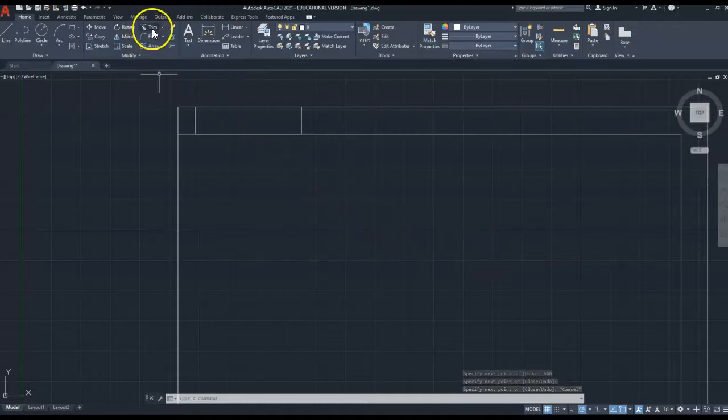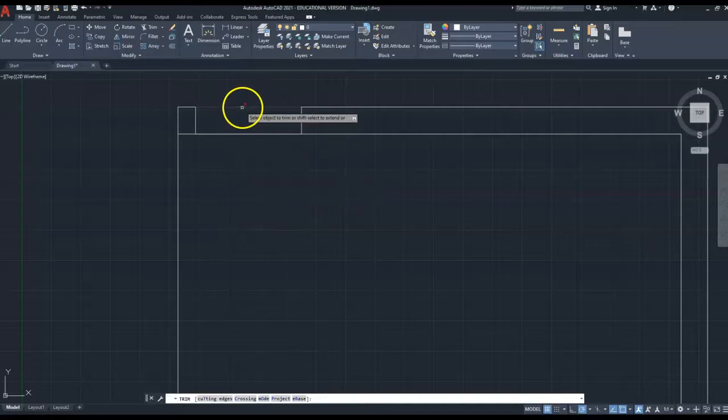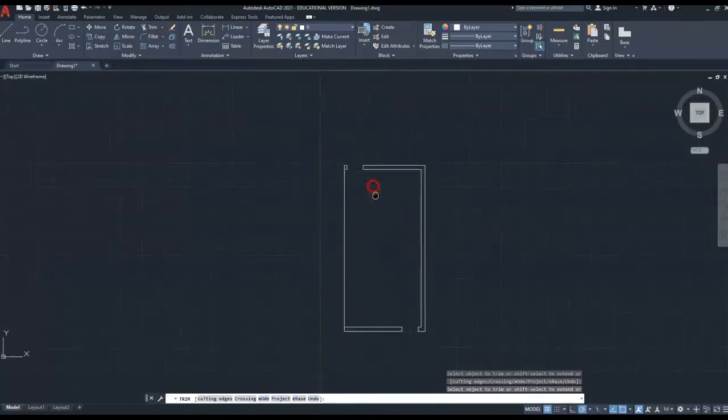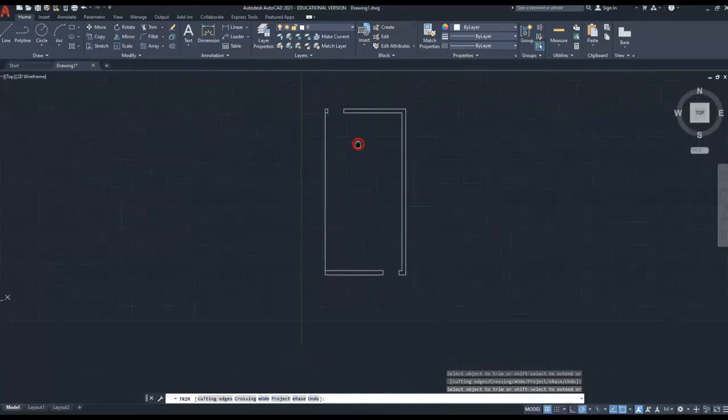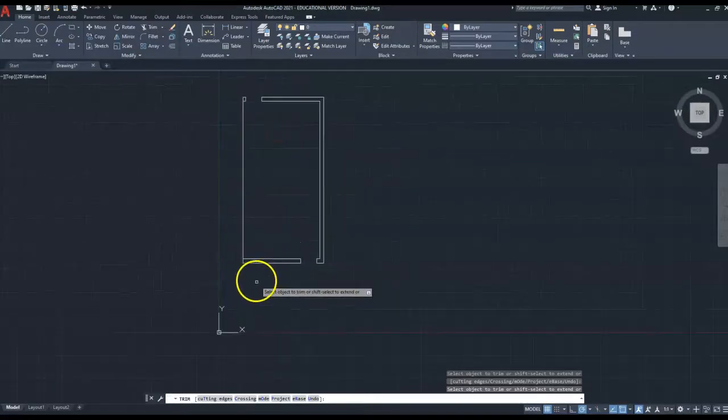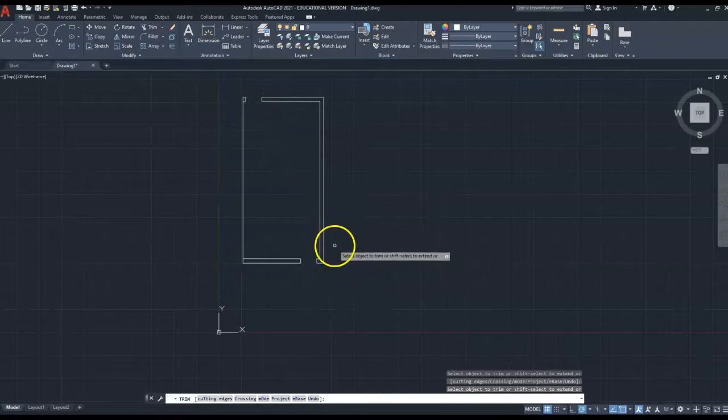So I'm going to go up to trim, and I'm going to select delete, and I've got to do that twice again because I've drawn 2 lines over each other. Jobs are good. Let's scroll out. So using the wheel, scroll back. Hold the button with the wheel down so I get the little black hand and I can move that. So now I've got a building and I've got 2 door openings, which is fabulous.